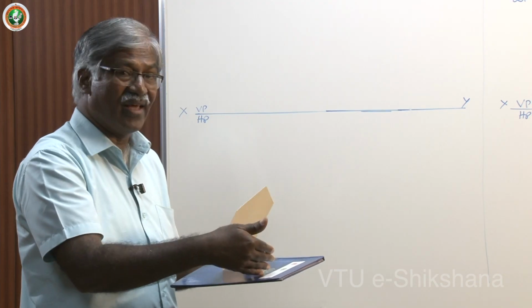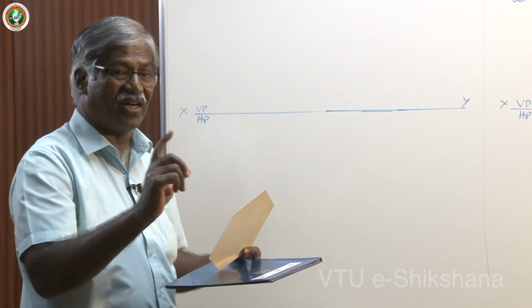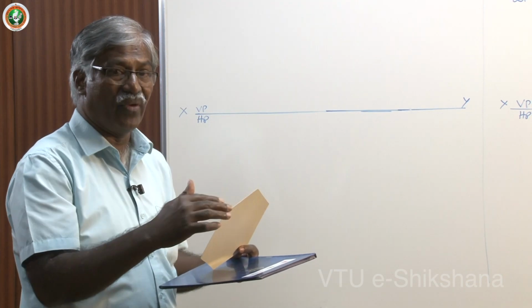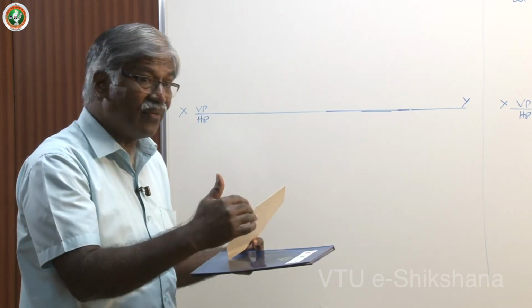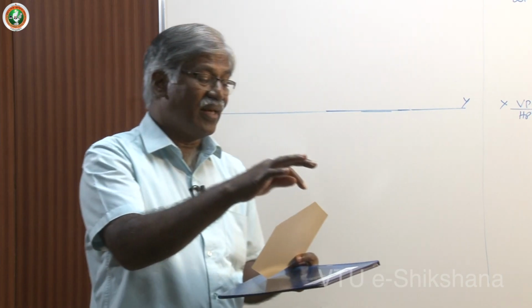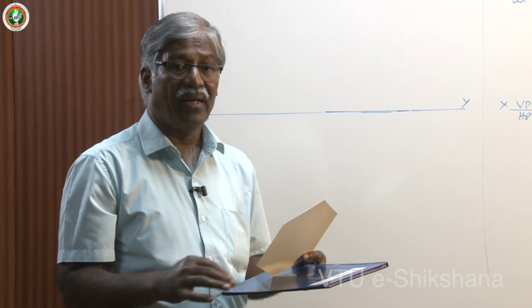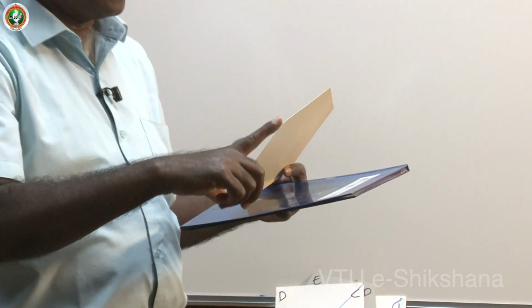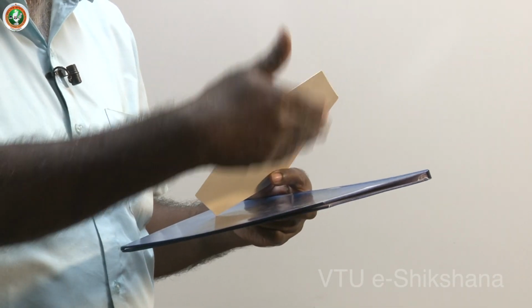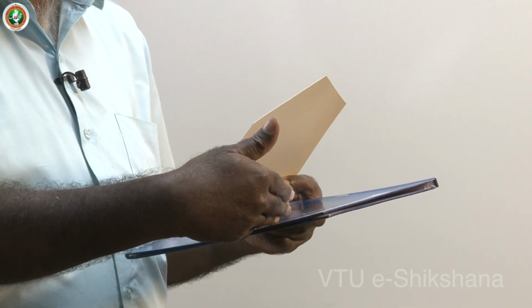Instead of giving inclination, they may give the top corner, just like a straight line problem. The locus of the moving end they will give. See here, corner on ground, and instead of giving the lamina inclination, they say the top corner is 30 mm above HP. What you have to do? You have to draw the locus, then take the front view length and cut an arc. Then you get the inclination automatically.